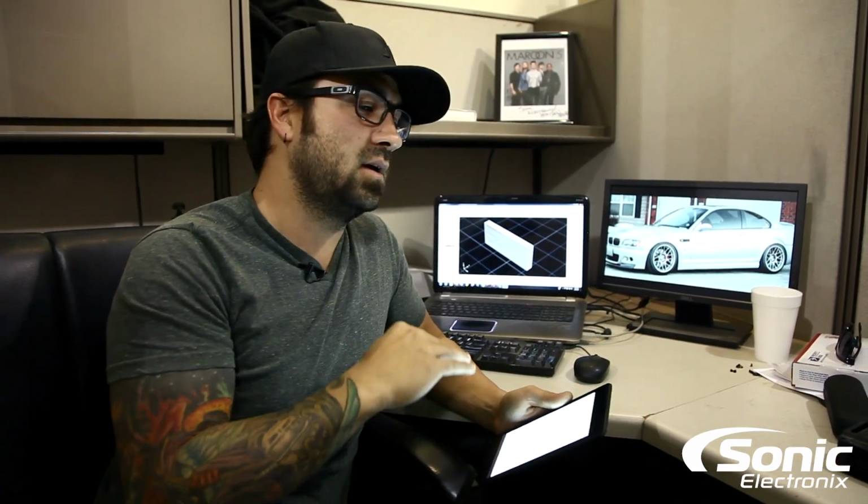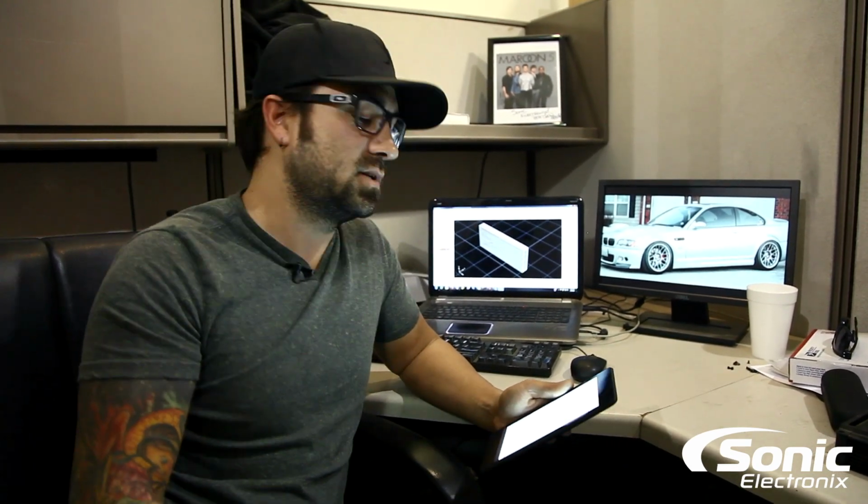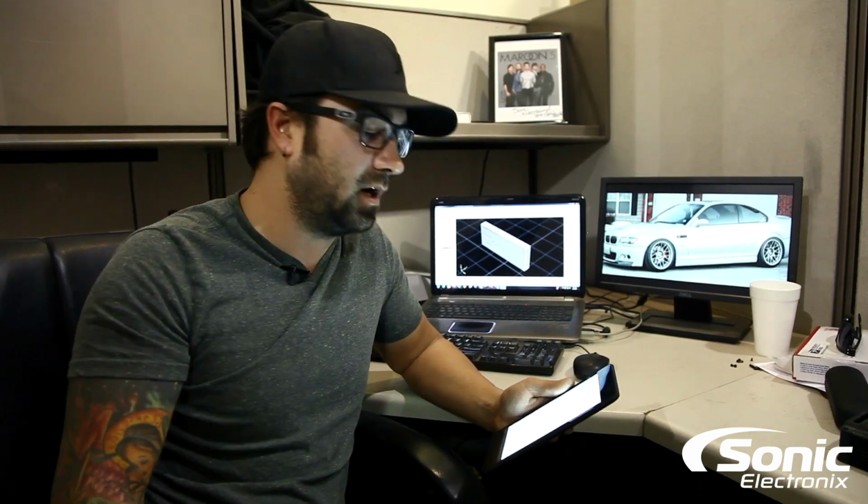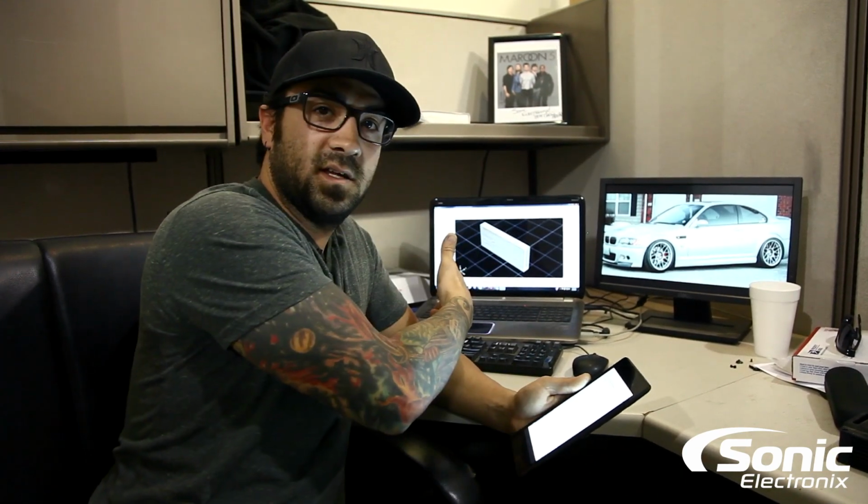So to sum it up, I'm sorry I can't answer your question specifically exactly that way, but I hope that you seeing how we do it and how we factor ports here will help you look at it in a completely different way. Everything's all intertwined together between the port area and the length and the tuning frequency, that in my opinion, and after using this program for a few years now, I can't say that one port area works for everything. But keep the questions coming. It's definitely a good question. I'm glad I had this to where I could actually show it to you, and hopefully that makes sense from kind of like a graph perspective.